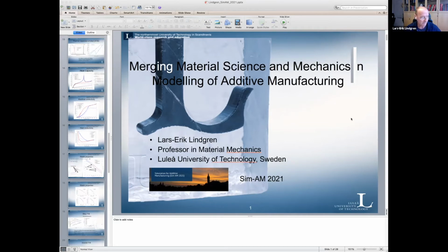And the problem, of course, is the measurement resolution and what kind of technique you're using. You would like to have a small homogeneous region, so you don't need so much beam time, for example, if you use that method. But in principle, you can do that. You can use the hole drilling technique. You measure an elastic unloading and have some model assumption to say what the stresses were.